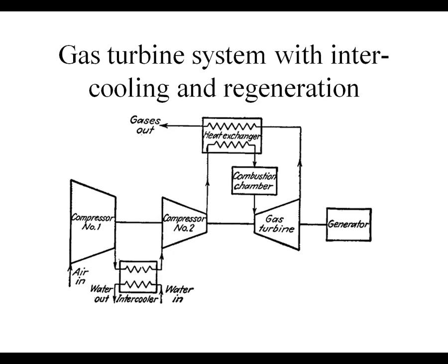And another idea is with intercooling. In order to realize a higher degree of compression, you use two compressors, but in order to keep the temperature under control, you must cool down the temperature of the air between the two compression periods.